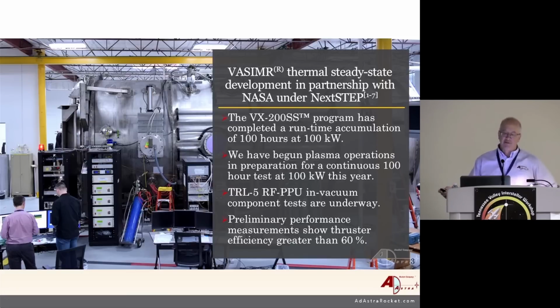Our PPUs are actually very simple systems compared to other electric propulsion systems because these waves basically are linear waves. There's some quasi-linear effects in that you get slow changes because of power and things like that, but you don't have any real instabilities that you have to fight like you have to fight when you separate the system out in what I would call an unnatural mode.